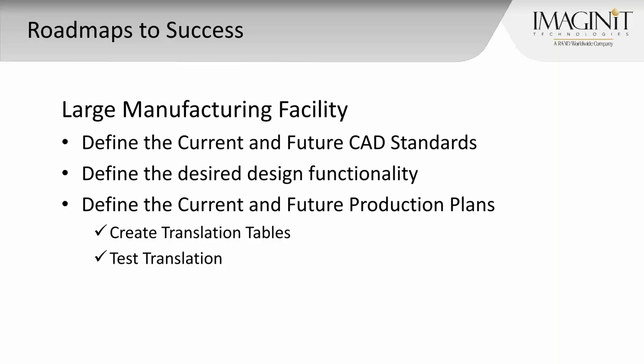We always want to test those translation tables. And so we will take a folder structure, a sample folder structure. We will run those translation tables through there. It is an iterative process because we always encounter things that are not handled by the translation tables. So as I said, every project is unique, and we find something a little different in every project that we do. And so we test the translation on a small scale, run it, QA/QC it, maybe a couple iterative processes till we feel it's comfortable with that, and then we'll do a large scale folder translation and go through the same process. Again, run it, QA/QC a percentage of those files for that, and make sure that the translation tables are handling that, and we'll do that in a discipline by discipline process if necessary for the translation tables.